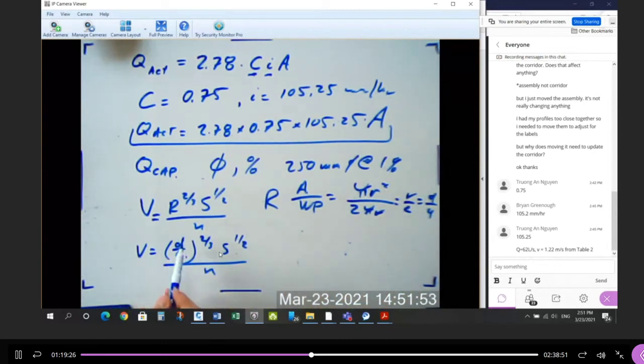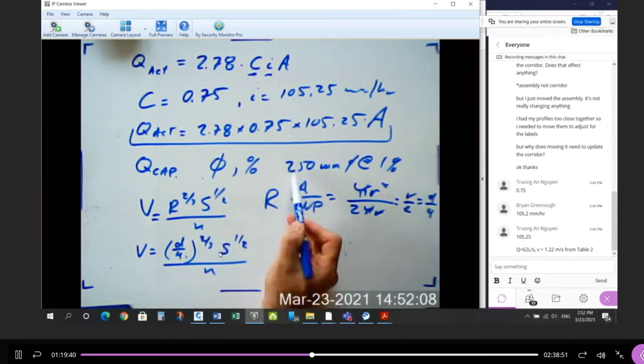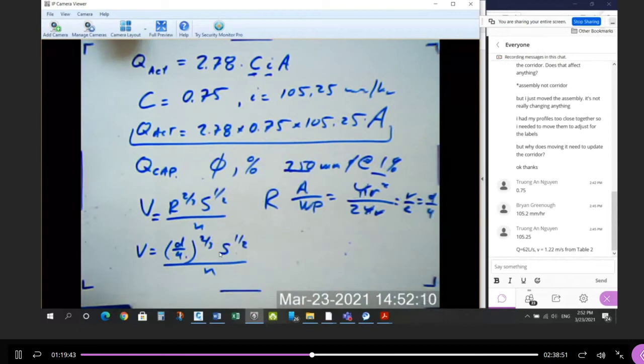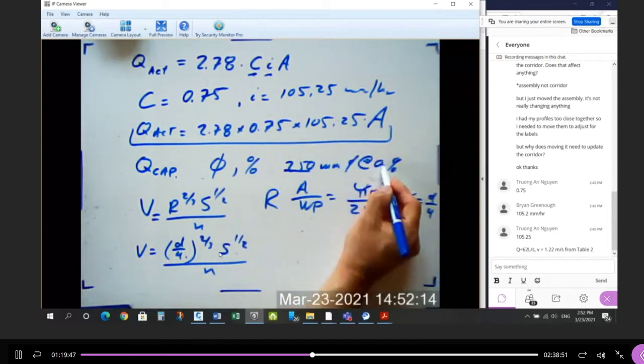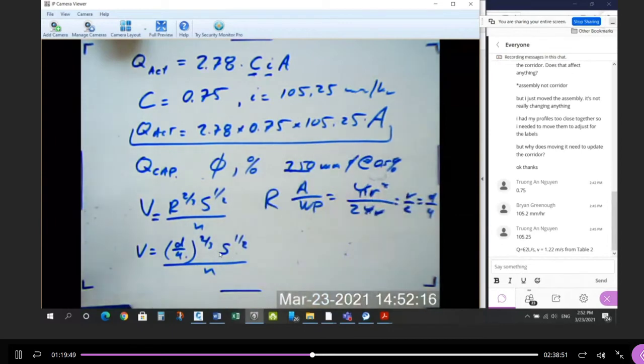This is how you calculate the velocity. When you take the diameter, this has to be in meters. The roughness coefficient for either PVC or concrete pipe is always 0.013, and the slope is in meters per meter. So a 250 pipe at 1%, sorry, not 1%, 0.5%. I'm going to use 0.5%. Trong, can you look that up again? 0.5%, not 1%.